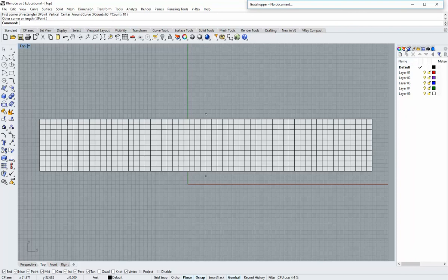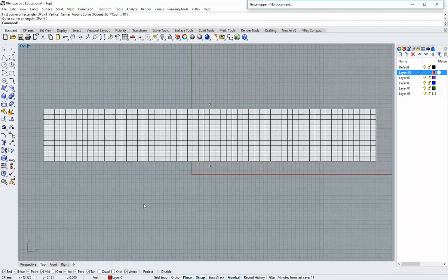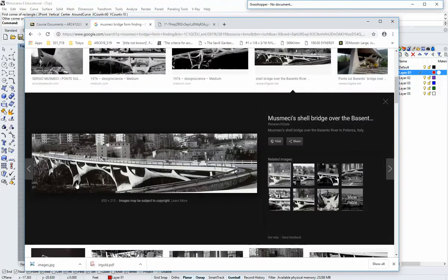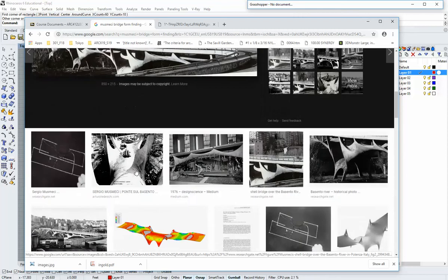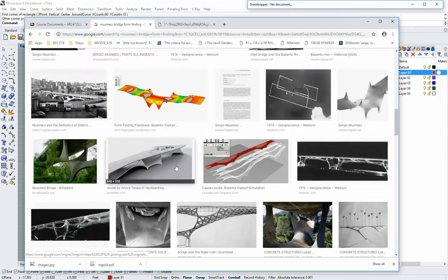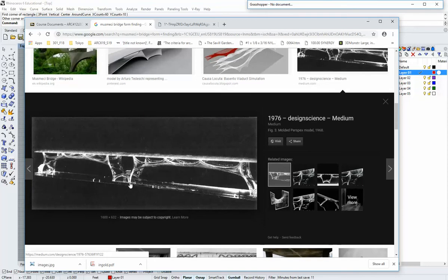Now I'm going to grab a different layer. I'm going to go to layer 1, which is the red layer, and start laying in some points. These points are going to end up being our contact points for both the ground and the top part of the bridge, so they're all going to be anchor points. We're going to draw out the points for the anchors that touch the ground, and then use a similar constraint to lift those points up to touch up here, and then down below again. We just have to plot out those points first, and then we can do the simulation.